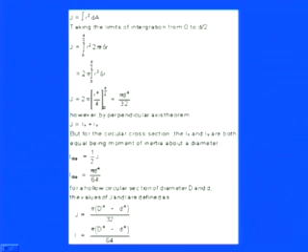So, you see these two formulas are very important for solid as well as hollow circular shafts, because once you know the values of J and I, you can easily calculate the different properties described for the beam, because you have a circular cross section. All those properties, the bending stresses and the bending moment, depend on the values of I and J. So, we need to calculate those things, and for the calculation of I and J, the parallel axis theorem is very important, along with the perpendicular axis theorem.